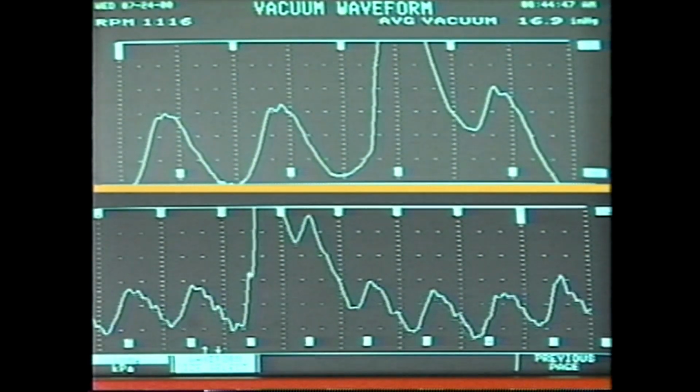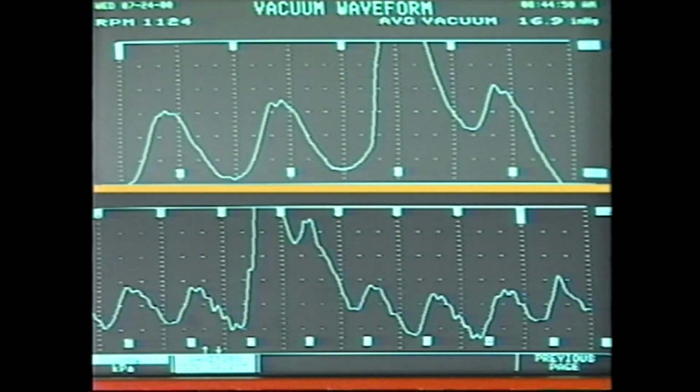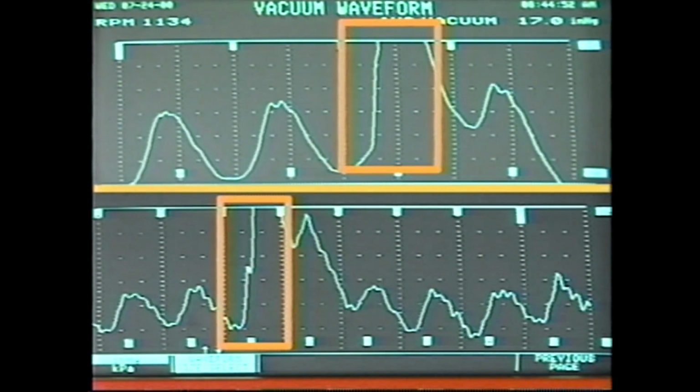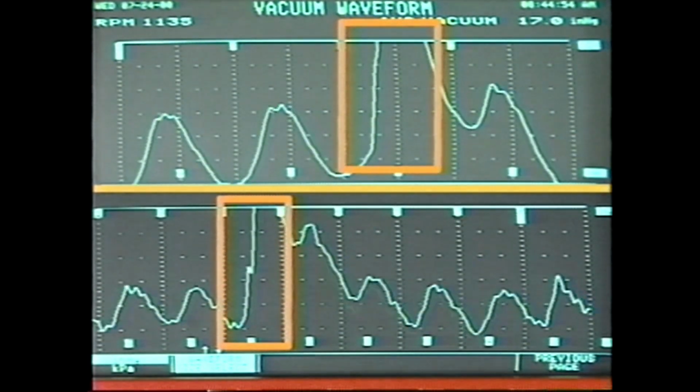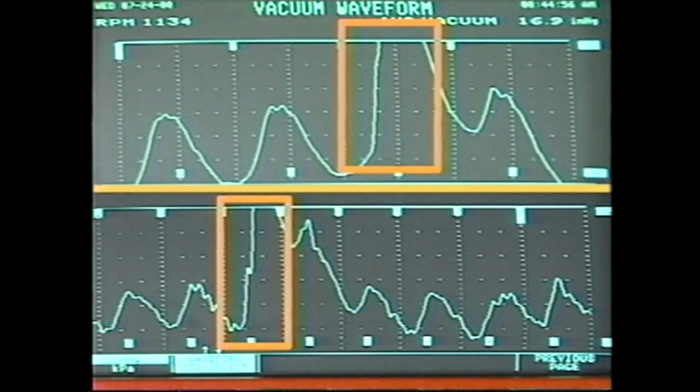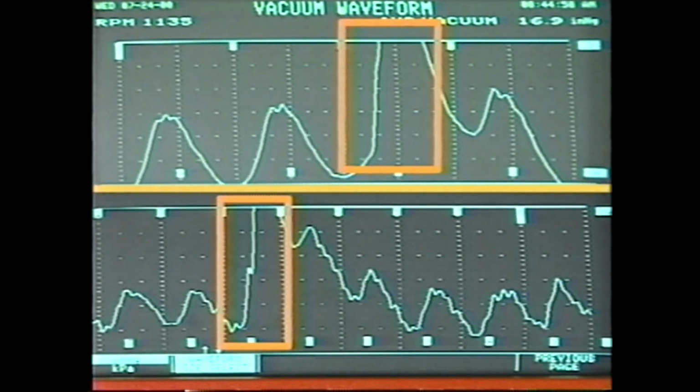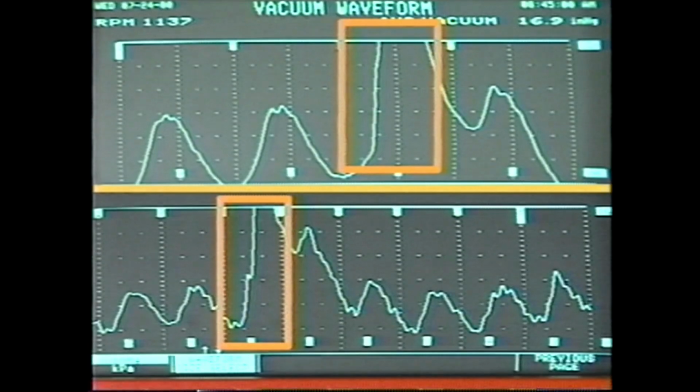In this pattern, a worn exhaust cam lobe creates an excessively high peak. A steep rising slope can also be caused by excessive lash, a bent push rod, or broken exhaust rocker arm.